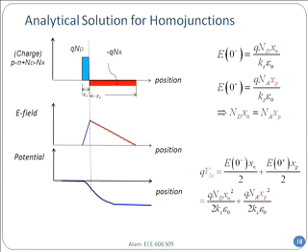And what is the area under the curve? The blue triangle, it will be half multiplied by the height multiplied by the base. That's the first term on the QVBI on the right hand side. Do you see? This half for the triangle, Xn and E0 minus. And similarly, E0 plus Xp divided by 2, because that's the red triangle. And when you sum it up, E0 minus and E0 plus, you have already calculated on the top, you put it in. Am I done?